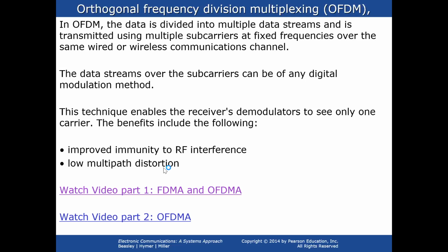Suppose a signal is to be transmitted over a bandwidth B and carrier frequency FC. Then symbol time for this would be TS equal to 1/B. For a single carrier wideband channel of, let's say, 1 MHz, the symbol time will be 1 microsecond. Given that the delay spread of the channel is 2 microseconds, the combined symbol time would be 3 microseconds, which means delay spread occupies 66% of the combined symbol time, thus reducing the efficiency of the channel by 1/3.